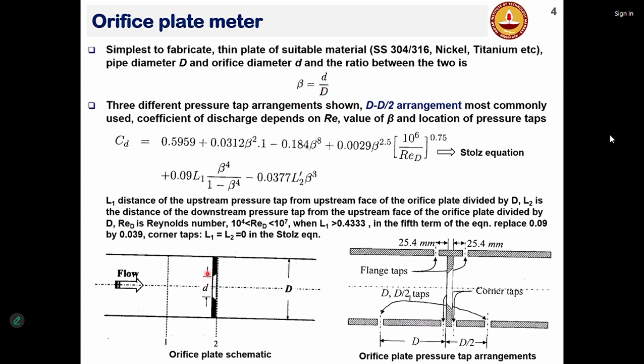Now, there is a reason why this orifice plate has a diverging slot, not just a straight slot. This is a divergent slot to basically minimize the losses that happen here. If you make it straight, the losses will be very significant at the downstream corner. So that is why they make this diverging. And you basically insert this plate there.